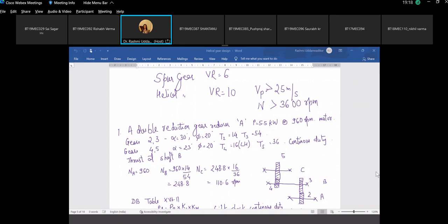Yeah. Oh, sorry. Right. Come on, say it again. What do you mean by thrust? Now I don't know. Abhijit? Parallel to the shaft, maybe. Parallel to the shaft, yes, which is axial force, which is produced only in case of helical gear, the undesirable thrust or the undesirable force which is coming because of the helix angle, that is Fa.